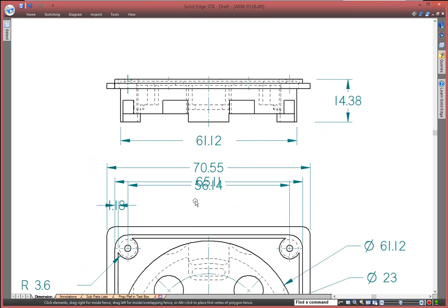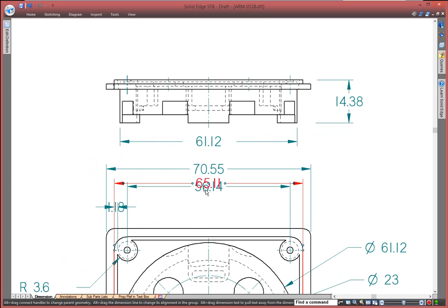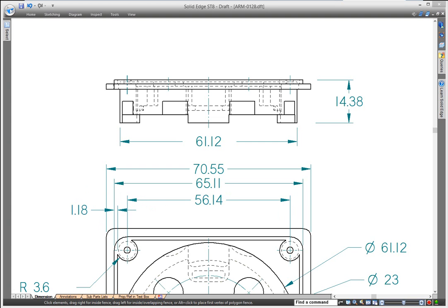The center handle allows us to quickly move a dimension, like this one here. We pick up the center handle there. Even though it's hidden behind there, we can move that down. If we insert a jog into dimensions, when we're taking it out, you'll notice it snaps to the non-jog position, which removes the jog. Here, all we need to do is move this dimension down and across.